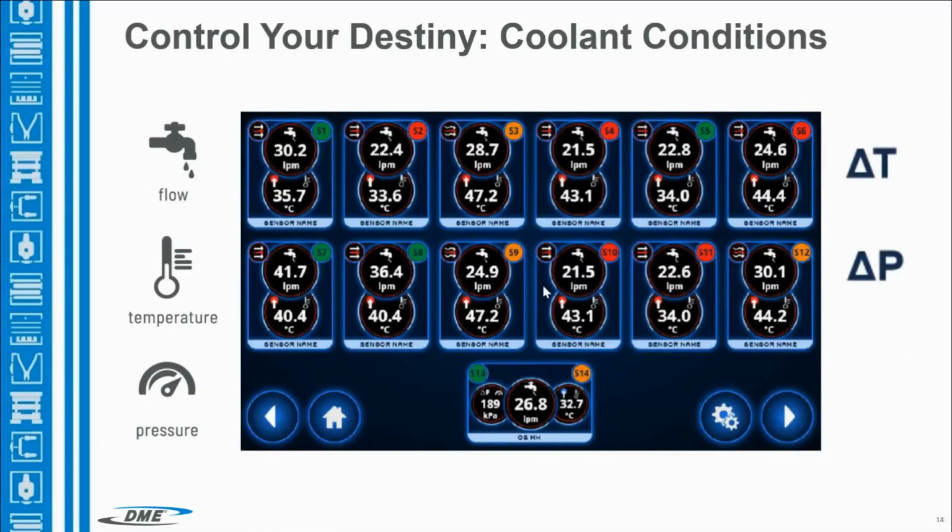And that's where we really want people to take a step back and look at your system. You monitor melt temperature, the melt variables, very well. You monitor the flow of plastic into the mold very well. You monitor pressure extremely well. What do we really monitor on the coolant circuits of our tools? As a custom molder, we would monitor the water temperature from the temperature control unit. We would monitor our cycle time and our cooling time, and that's really what we controlled on our water.